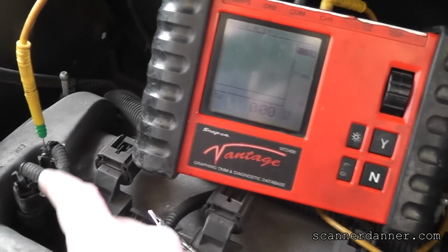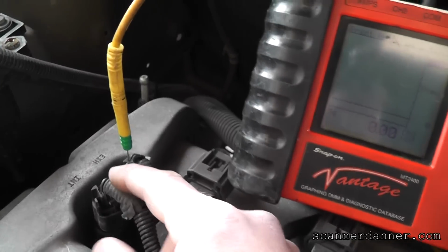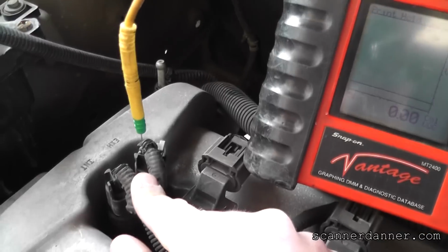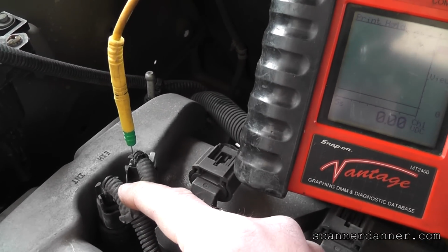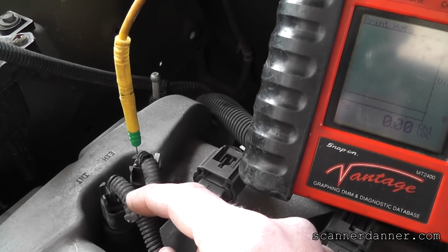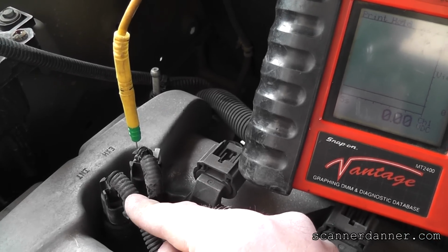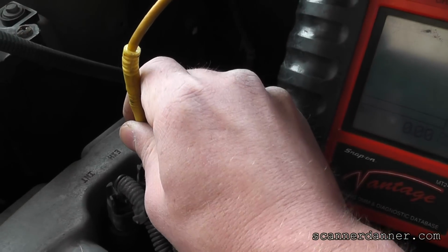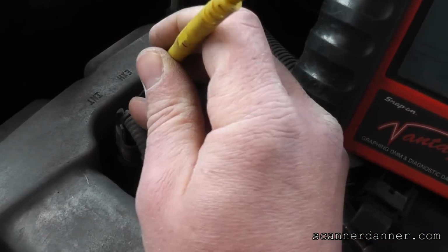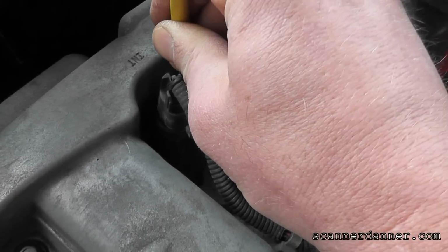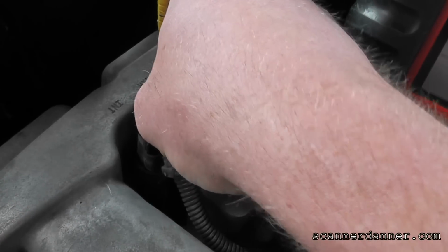Remember the bias voltage on these? Power side switch circuitry, bias voltage. Section 3, I have this information, bias voltage. It's really, really cool that we can use this for a diagnostic purpose. And you know, it's a shame the engineers don't give it to us. 0.93 of a volt is the bias voltage that I saw on the intake cam. Let me show it to you one more time. Back probe the intake cam solenoid, sorry, I'm calling it the cam.